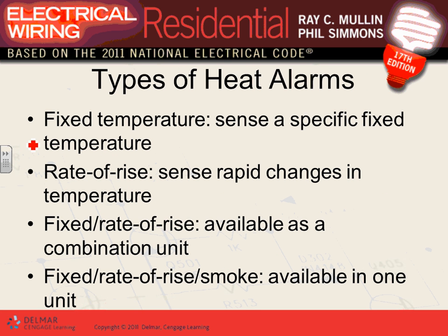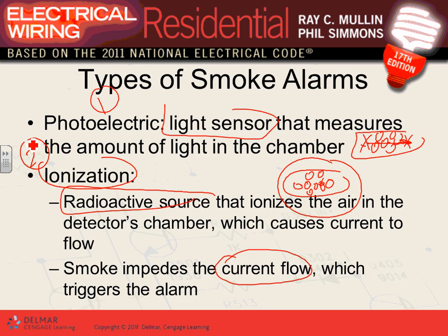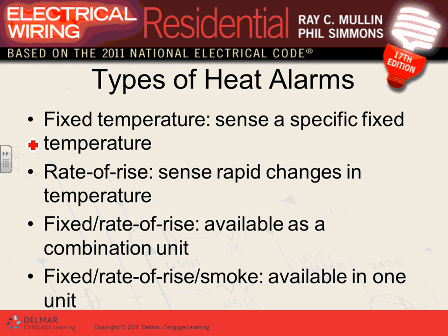So these are your smoke detectors. They look for smoke. How do they sense the smoke? The smoke will accumulate in a little chamber, right? And that chamber has a current, either the photoelectric one or the ionization one. When smoke prevents that current from moving, it sends a signal. That's the means of sensing that there is smoke in the area.